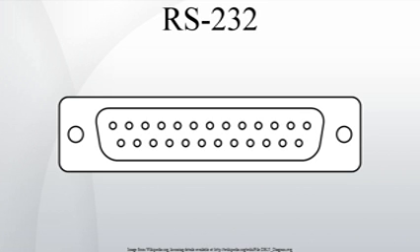Signals. The following table lists commonly used RS-232 signals and pin assignments. See RS-232C serial port pinouts for non-standard variations, including the popular DE9 connector. The signals are named from the standpoint of the DTE. The ground signal is a common return for the other connections. The DB25 connector includes a second protective ground on pin 1. Data can be sent over a secondary channel, when implemented by the DTE and DCE devices, which is equivalent to the primary channel. Pin assignments are described in the following table.